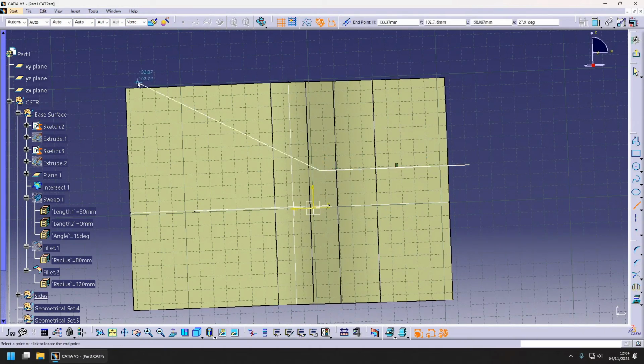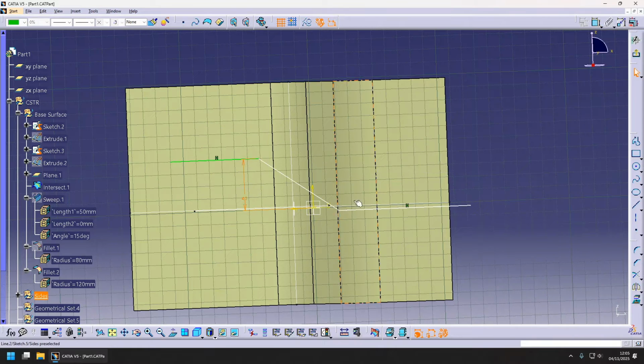I'm designing these walls in a single sketch because I wanted to go a little bit faster. But if I knew this was a part that I needed to change later, I would make them 3 surfaces and join them with fillets.